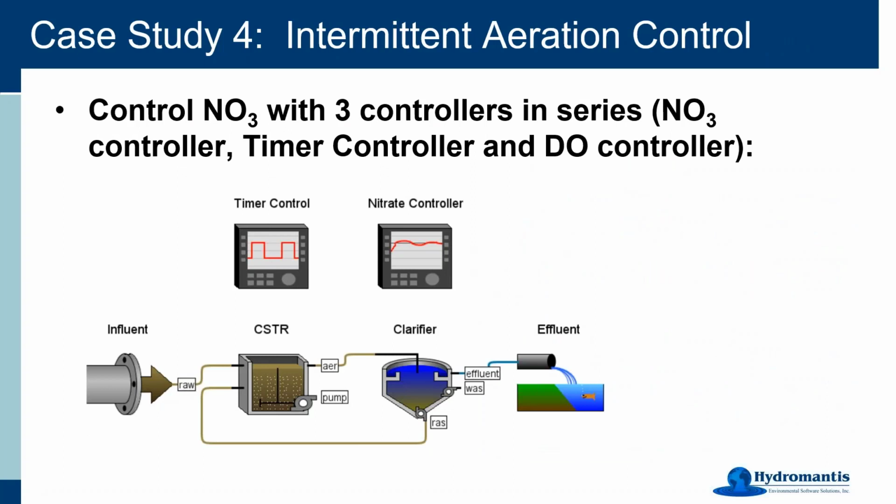Okay, so that's ABAC. So now we're on to the last one here, which is intermittent aeration control. I've seen this at quite a few plants. It's certainly come up in several industrial wastewater situations that I've seen where you have very high loading, or places where you need to do nitrification and denitrification, but I'm not really set up to have internal recycles or long plug flow systems that I can stick an oxygen on the front.